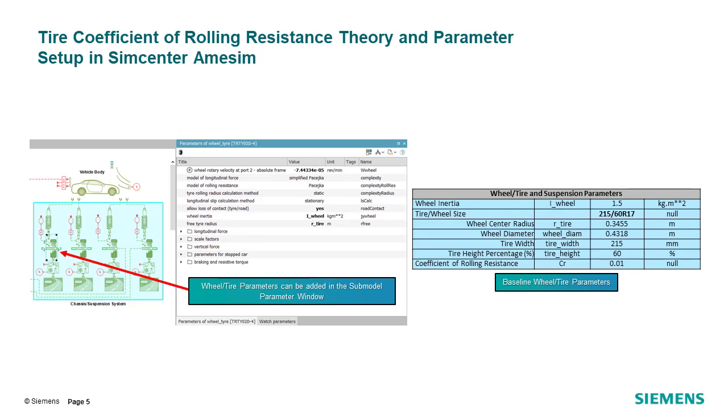Tire rolling resistance is defined as the force required to maintain the forward movement of a tire in a straight line at a constant speed. Tire rolling resistance coefficient is calculated by dividing the measured rolling resistance force by the tire size's prescribed load during the test. Tire rolling resistance force is calculated in pounds or kilograms of resistance.